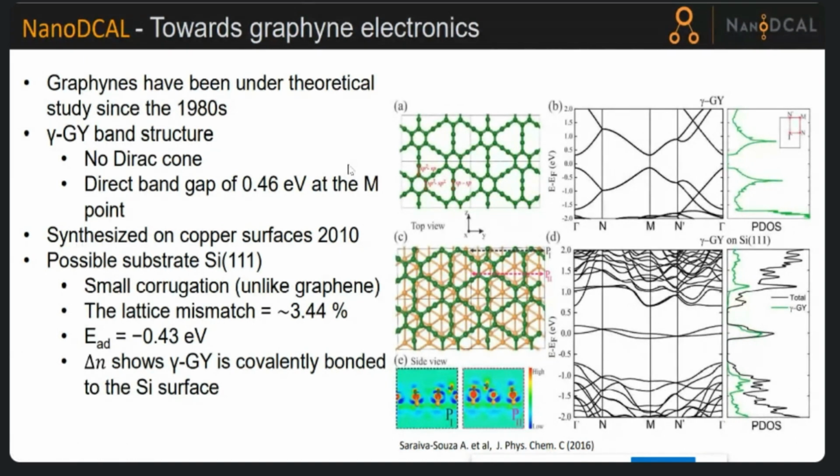It is also possible to define the structure on different surfaces. Like, you want to simulate the graphene sheet on a particular surface plane. So different 100 possible substrate, 111 possible substrate, find the lattice mismatch, adsorption, and covalent and non-bonded interactions. Like you can see here, this is one layer, and then another MoS2 layer you can create, and band structure and other characteristics are plotted with different 1D plots, 2D plots, three-dimensional plots. All these things can be plotted.